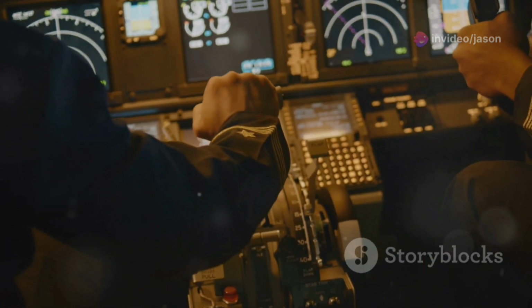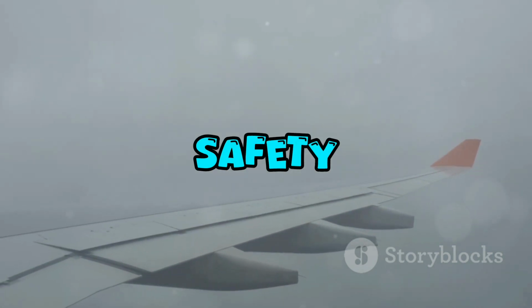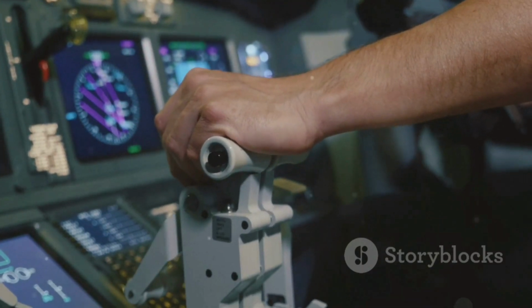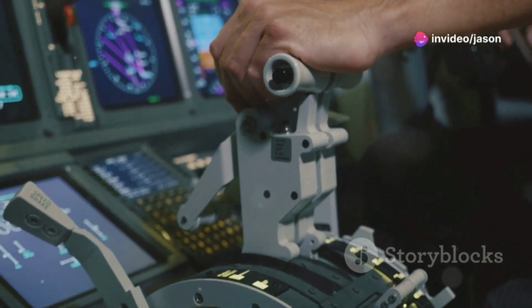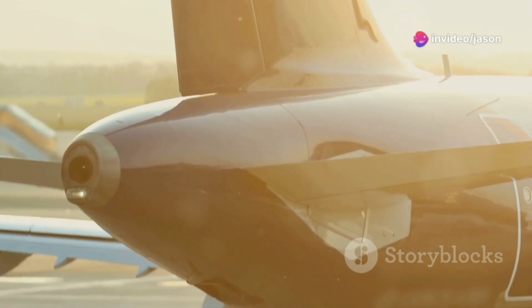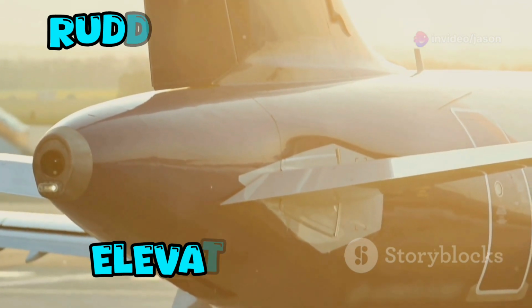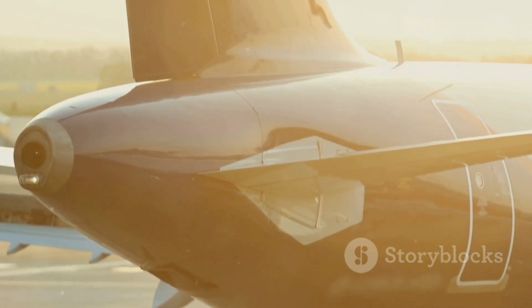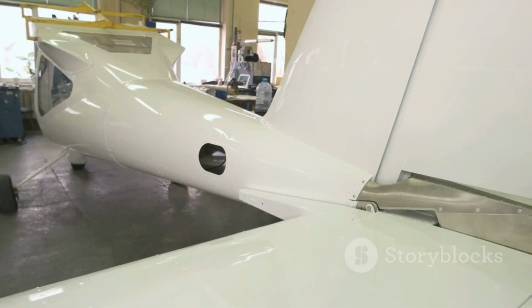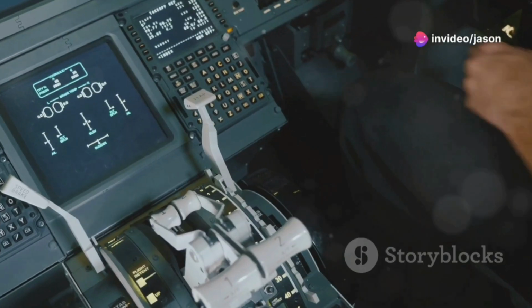Safety first, aerodynamics and flight stability. Aerodynamics is not just about efficiency, it's also crucial for safety. An aircraft's stability and control in the air are directly related to its aerodynamic characteristics. The design of the wing, tail surfaces, and control surfaces such as ailerons, elevators, and rudder all contribute to an aircraft's stability and maneuverability. For example, the tail fin and rudder help to control yaw, which is the side-to-side movement